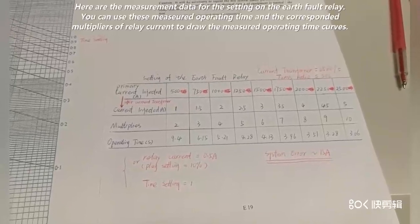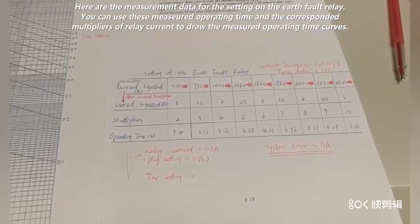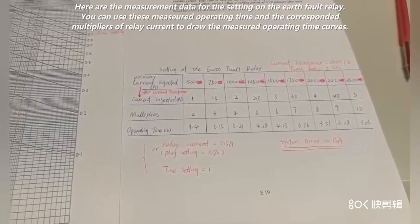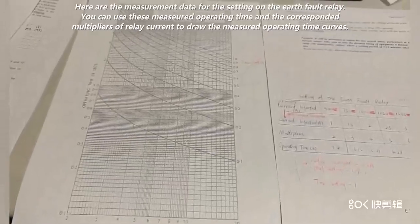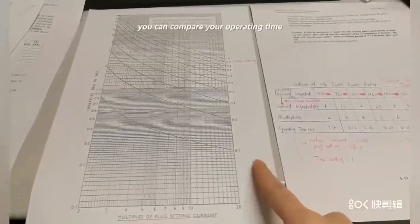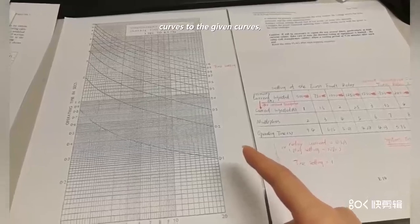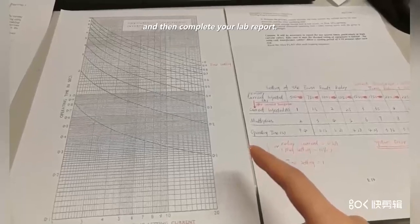Here are the measurement data for the setting of the Earth fault relay. You can use the data of operating times and the corresponding multipliers of relay current to draw the measured operating time curves in this diagram, and then compare your operating time curve to the given curves, and complete your lab report.